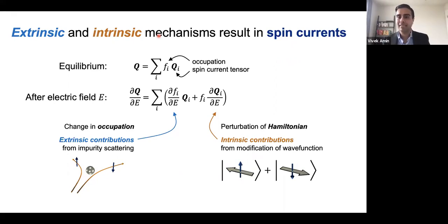As you already mentioned, if you change the thickness of the layers, you can try to look at the intercept of certain data and try to figure out whether you have an interfacial contribution or a bulk contribution. I think those experiments are very hard to do, and every single data point comes from a different device with potentially different interfaces within each device as well. So I think it's very hard to do in a bilayer.